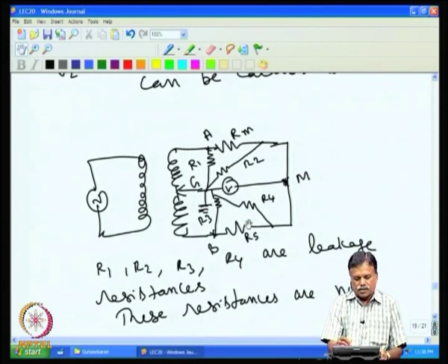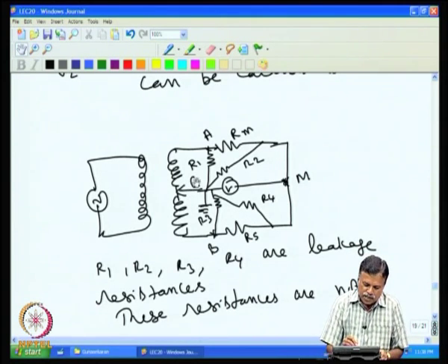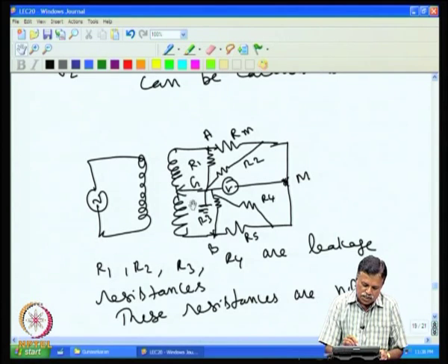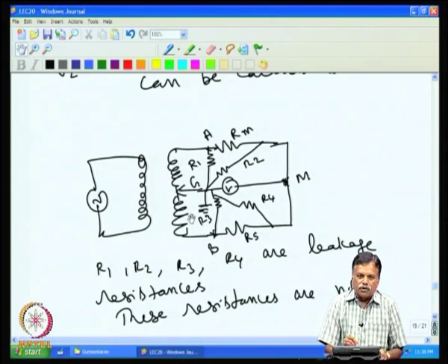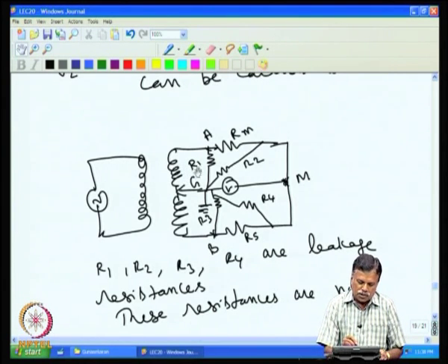Of course, one can manually balance and then measure this voltage and this voltage. Now, let us see how this measurement of voltage can be easily avoided by modifying the transformer slightly, so that one need not worry about measuring this voltage, because once you start measuring, the error in V1 and V2 will get in, and that will make the bridge not accurate.